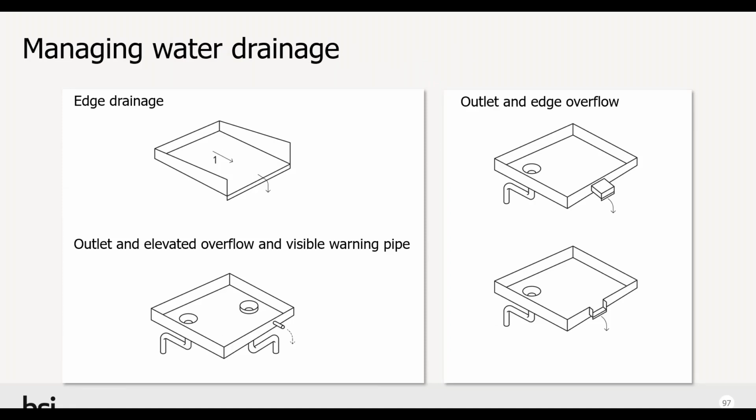This again shows some of the detailing available in the standard of how to do it properly and to make sure that the threshold design, the freeboard, and prevention of water ingress at openings can be achieved. Those are the principles of the strategy that we employed to create some advice for detailed design, and I hope that they will be useful. Thank you.